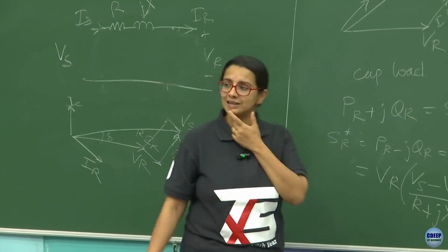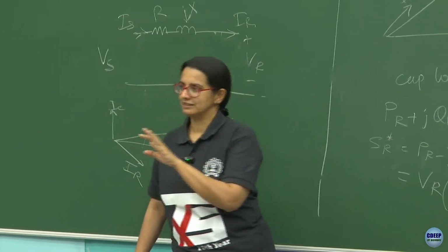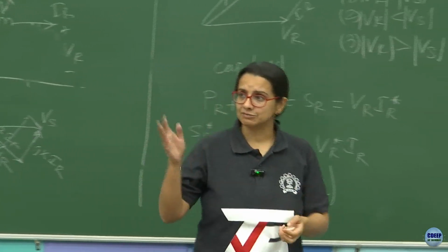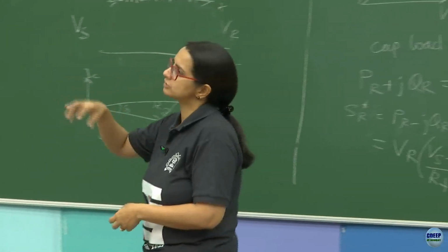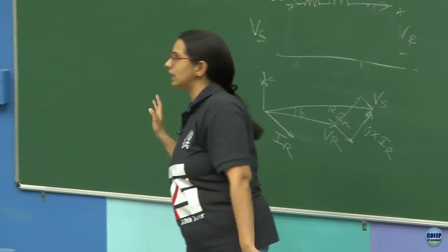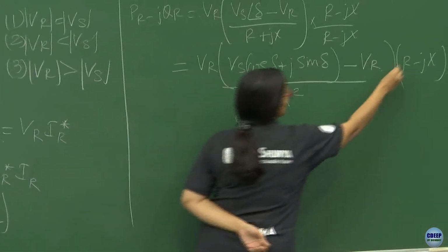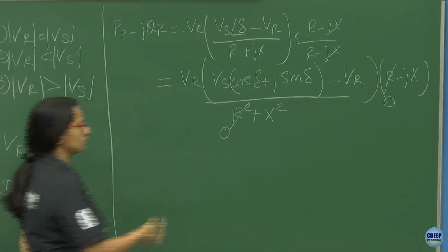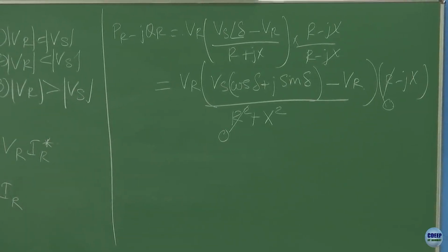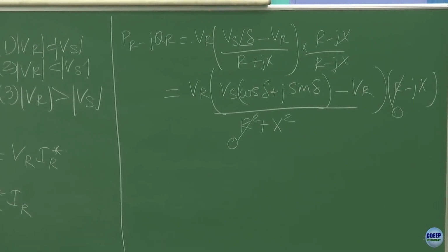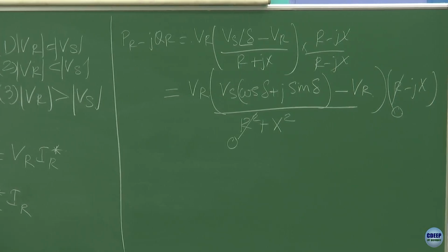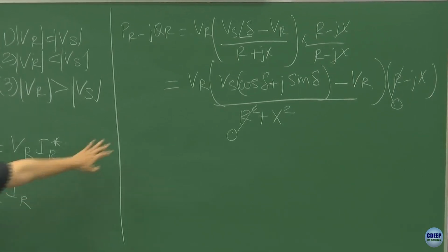And if you want to make it a bit easy, let's make it a bit easy. In large transmission systems, extra high voltage transmission systems, the R usually is much smaller than X. So you can ignore the R. Let's take R as zero. So make this zero, this zero, and now tell me what PR is going to look like. Again, we are setting this to zero not because it doesn't exist. It's small enough to be ignored, just like that capacitance. Okay? So, what would it be?